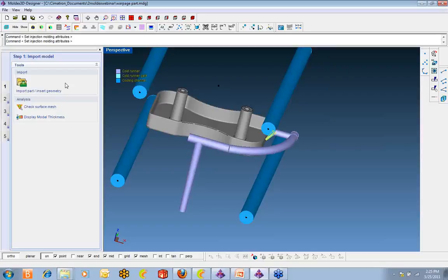Here we see a famous cologne product of Unilever. They took its cover into Moldex 3D simulation. For this part, the main problem is heat accumulation near the bottom. In order to cool down this area, additional time would be required at the cooling stage, increasing the cycle time. Moldex 3D provides excellent prediction for the high temperature area and the suggestion to enhance the cooling circuit design above the top of the part.